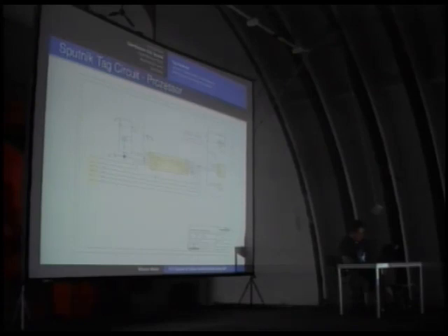This is the processor. I have a link for the data sheet. And then you know automatically, for example, you want to know how to toggle the clock pin. You follow the line for the clock pin. You see, okay, it's pin 10 and it's RC0. And then you look into the processor manual how to use this. But the normal use for you is, as I said, very simple. You just have to follow lines and look what is connected where.